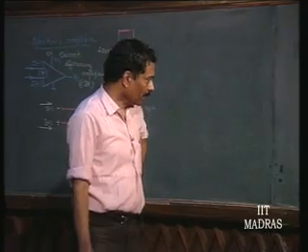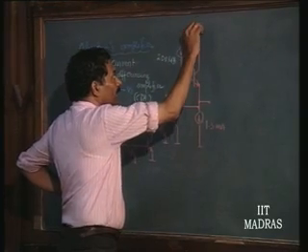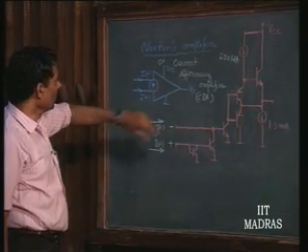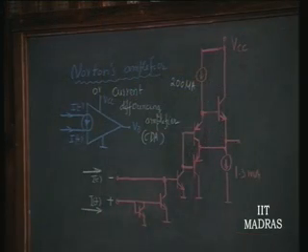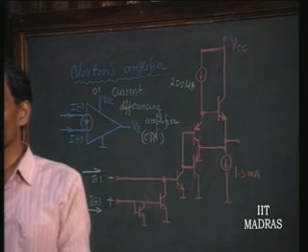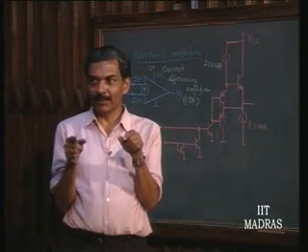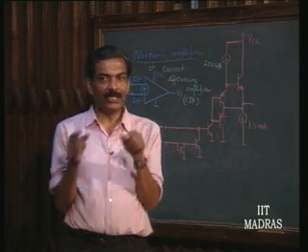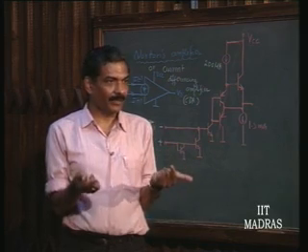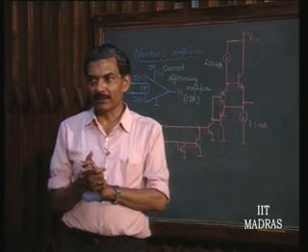So, the next topic for today is a very interesting general purpose amplifier called Norton's amplifier or current differencing amplifier. The amplifiers which we have earlier dealt with were primarily dealing with voltage difference, let us say V1 and V2 being the two voltages applied to the two terminals. Then V1 minus V2 was intended to be amplified, that is the difference amplifier that we had discussed. In almost every stage that we had thought of, we had used that concept.